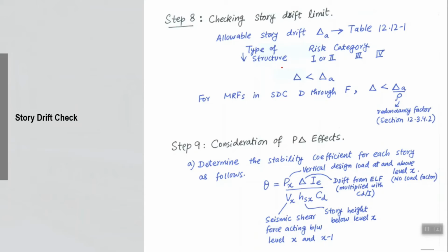There is an alternate design philosophy also called displacement based design, in which you start with an assumed or calculated design displacement and then calculate back those forces which will be produced in your structure when it undergoes that displacement, right? And then make sure that enough capacity is available in all the elements to handle those forces, right? Ultimately this will ensure that the elements will handle the design displacement. That is a separate design philosophy called displacement based design.